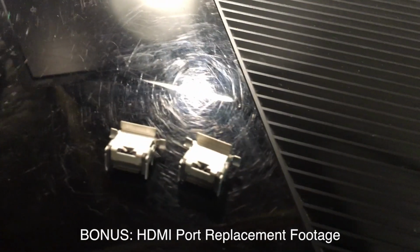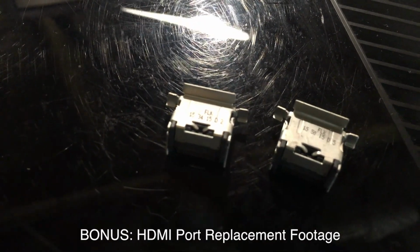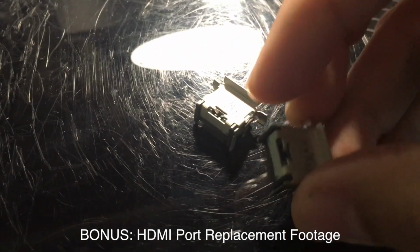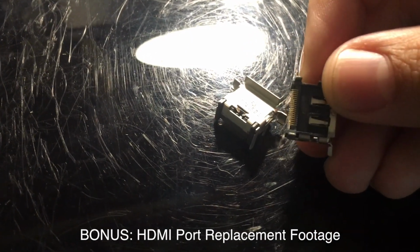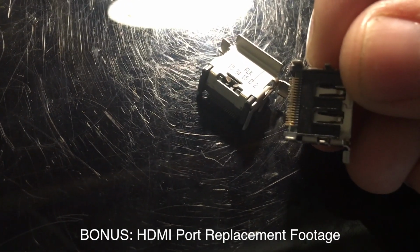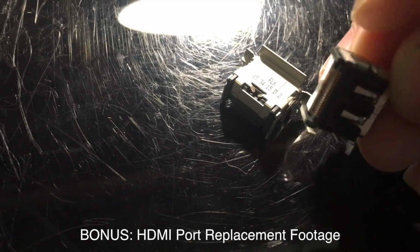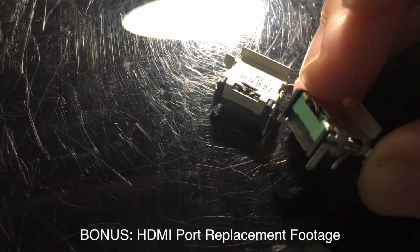But what this video is going to be about is the fact that we need to replace the HDMI ports. These are a couple of HDMI ports I got on eBay, I ordered 2 for $10. And what I'm showing you here is how tiny. There's 19 pins on here which need to be soldered. And then there's 4 pins that hold the actual port itself down to the motherboard.